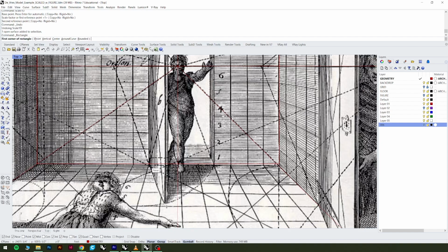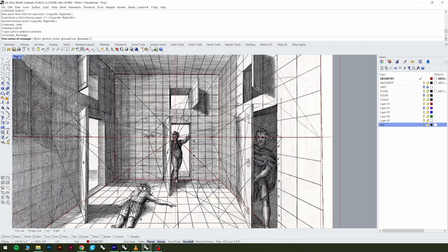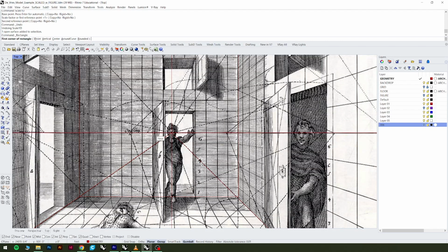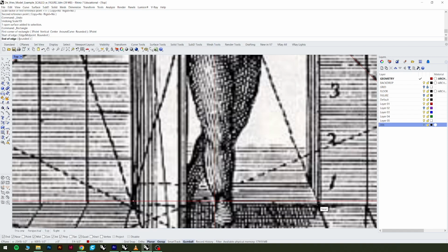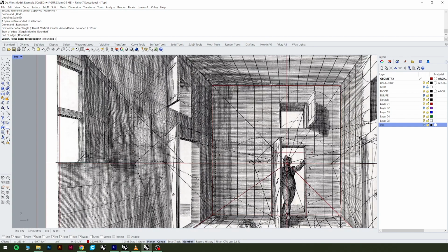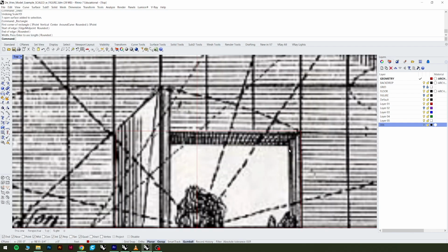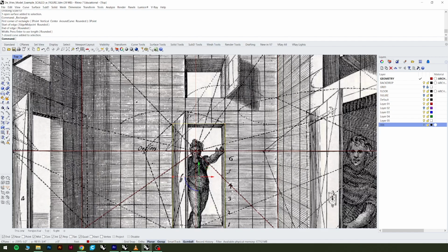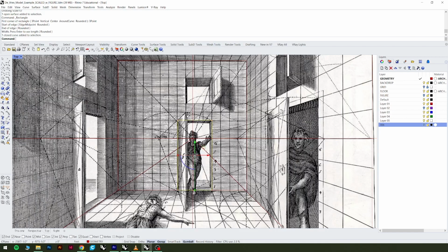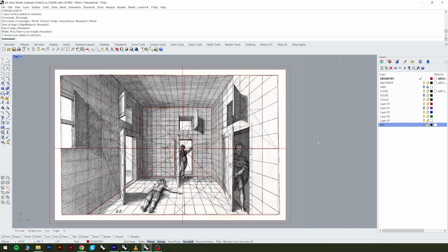So the thing that's useful is if a door is supposed to swing from its opening, I'm going to at least first assume that this drawing was drawn very well, and so I'll do a rectangle from 3 points, and I'll draw the door as if it's closed first, and then I will go into my next view a little later on in this video, and I'll rotate that rectangle and try to get it to line up, or at least see if it starts to line up with how the perspective and the camera is affecting this door in space.